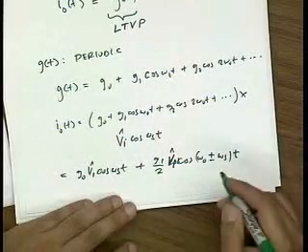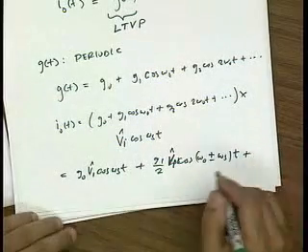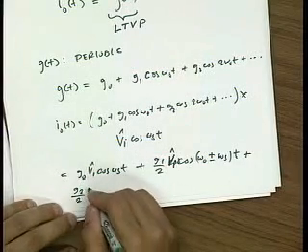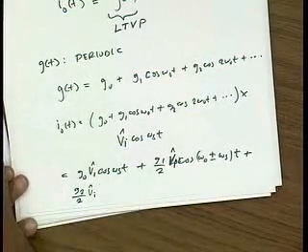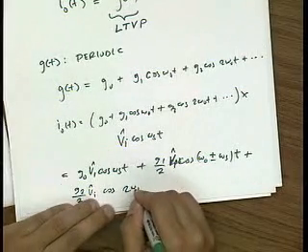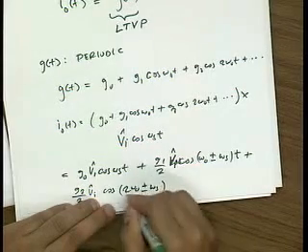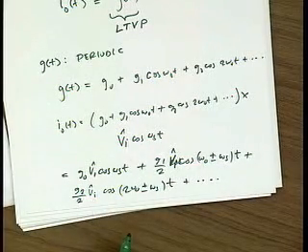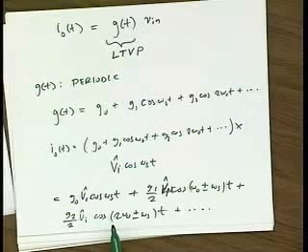That's kind of the ideal mixer multiplier that we talked about last time. And then G2, the input, gives us cosine of 2 omega naught plus or minus omega s t, and so on and so forth. So we can see that a linear time-varying periodic circuit is kind of a mixer that generates lots of products.